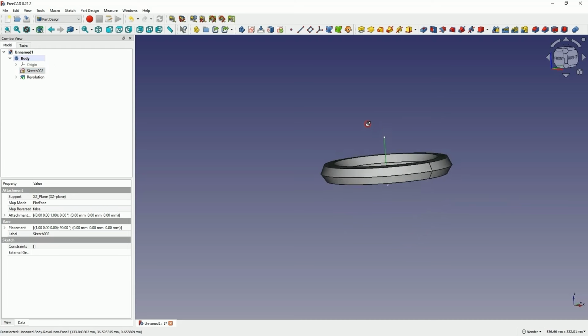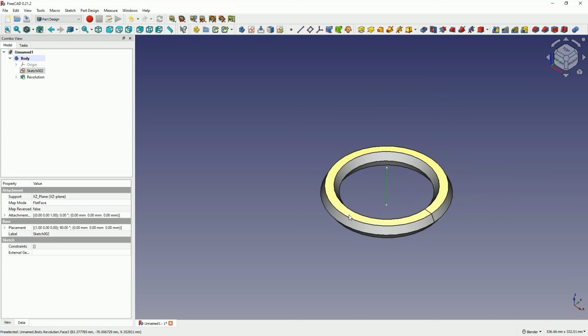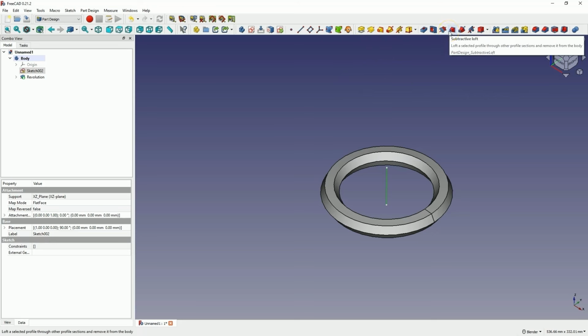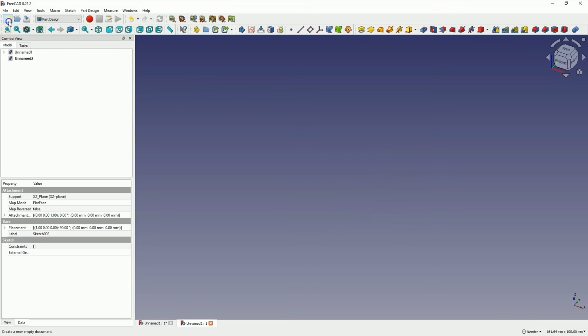And as for this operation, next to Extrude, this is one of the basic operations for creating 3D solids in 3D CAD systems. We will finish this example here, and now proceed to the next example. Just like in the case of the extrusion, where we create a solid by extruding a sketch, we have the pocket operation, where we remove material based on a sketch. Here we can also create a solid by rotating a sketch, as well as remove material by rotating a sketch around a specified axis. Now I will move on to the next example.